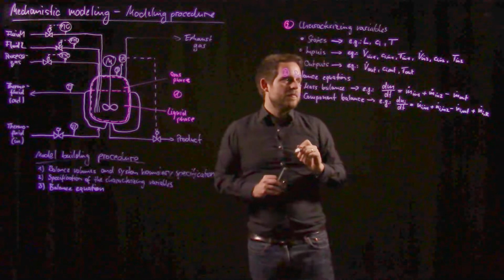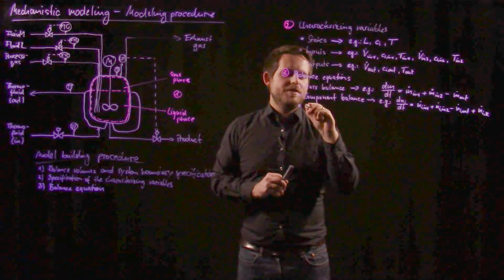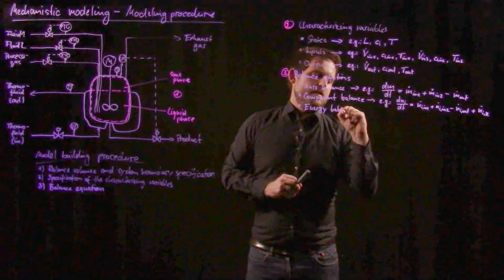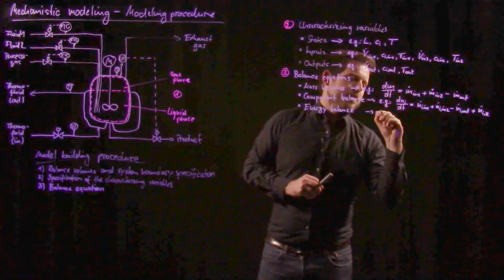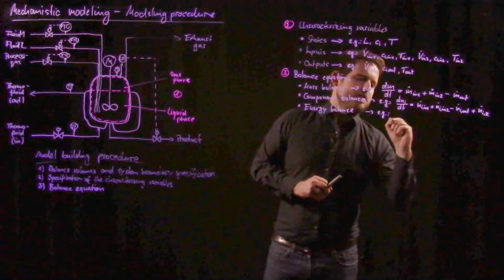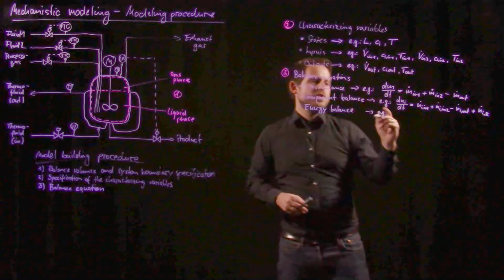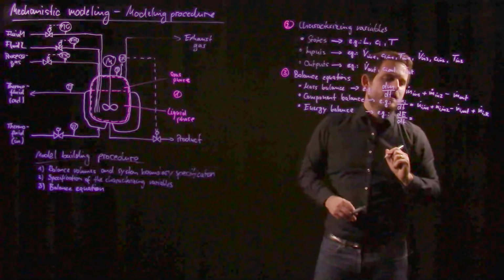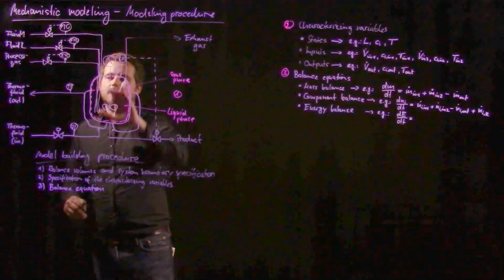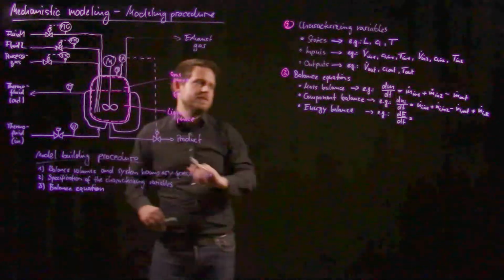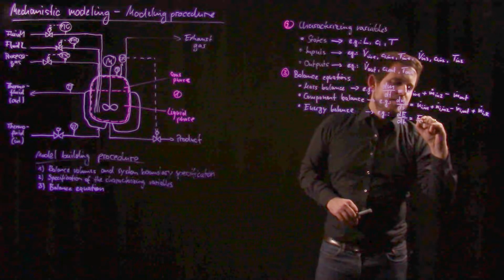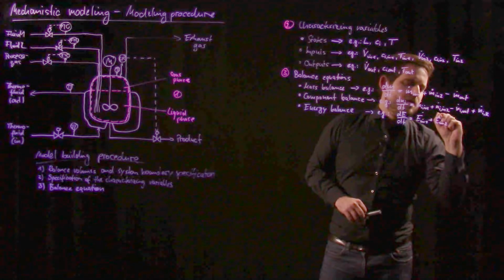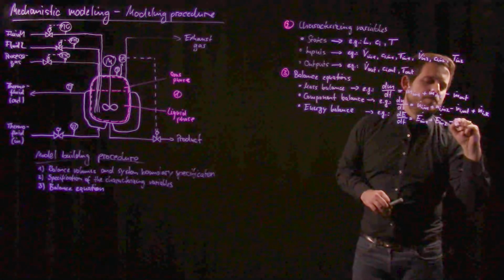And then the third class of balance equations is the energy balance. And again, here we have the same story. We have to ask ourselves, okay, we have the storage on the E. It's the energy that is changing in dependency of what goes in over this boundary here into my balance volume. This is the energy in 1 plus the energy in 2 minus the energy flow out.